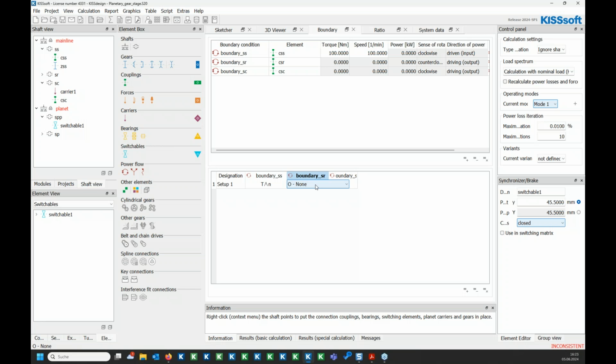So it needs 3 definitions, but not 2 torques and 1 speed. Instead, we need 2 speed and 1 torque definitions. And this can be realized with the definition of the speed at the boundary on the ring, for example. In most cases set to 0, but it depends on the application; you can also have some speed here. If it's stationary, as mentioned, there is this option with the own input of the speed, and then the output torque and speed values can be calculated.